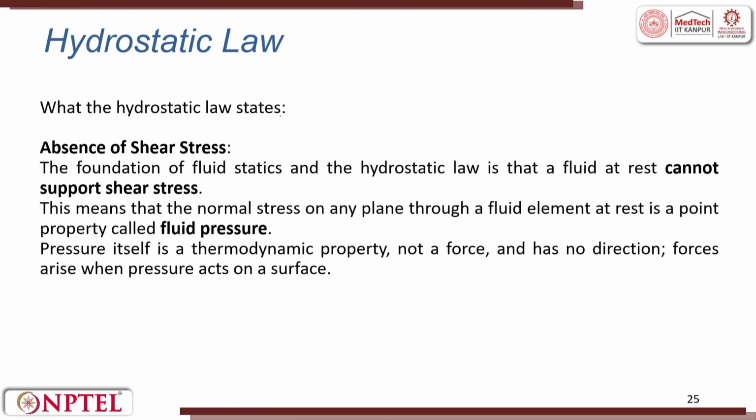What does the hydrostatic law state? It talks about the absence of shear stress. The foundation of fluid statics and the hydrostatic law is that a fluid at rest cannot support shear stress. This means that the normal stress on any plane through a fluid element at rest is a point property called fluid pressure. So the absence of shear stress is the important point. This pressure itself is a thermodynamic property, not a force, and it has no direction.